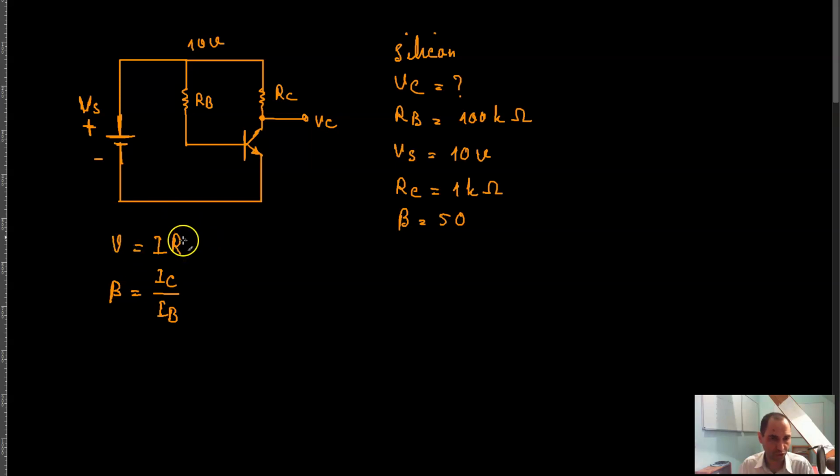I have the voltage drop, I have the resistance. I already know how much voltage drop there is across this resistor, and as a result I will be able to calculate the voltage at this point in the circuit, which we can call the output voltage, V of O or V of C, or whatever you want to call it.